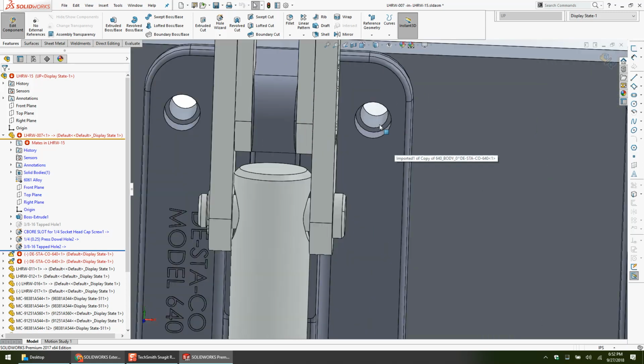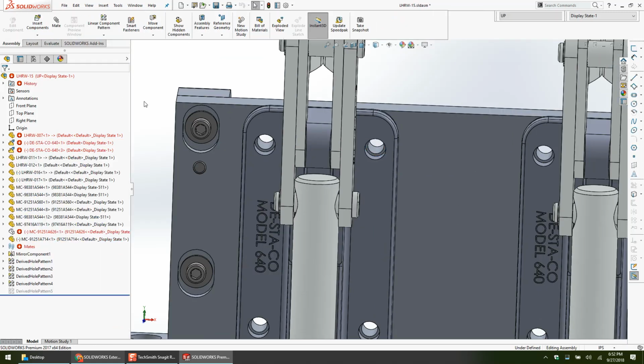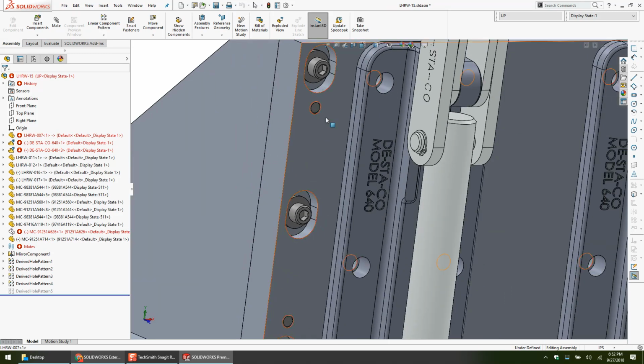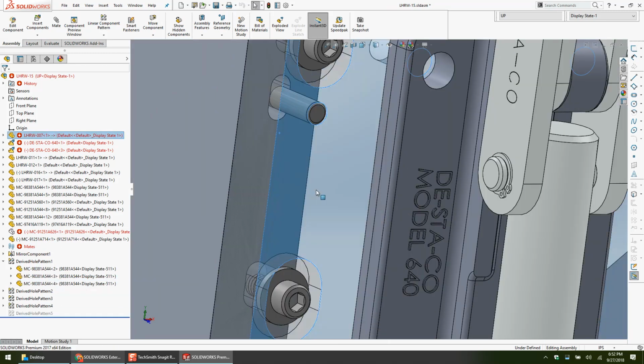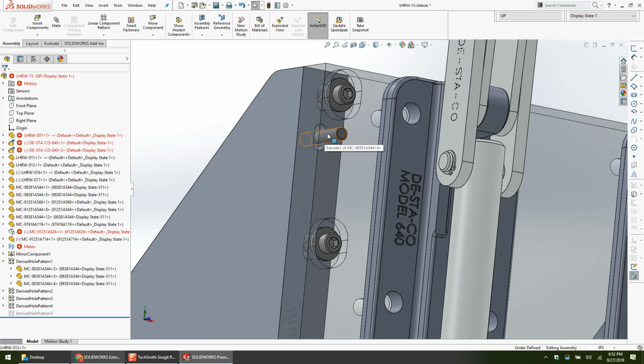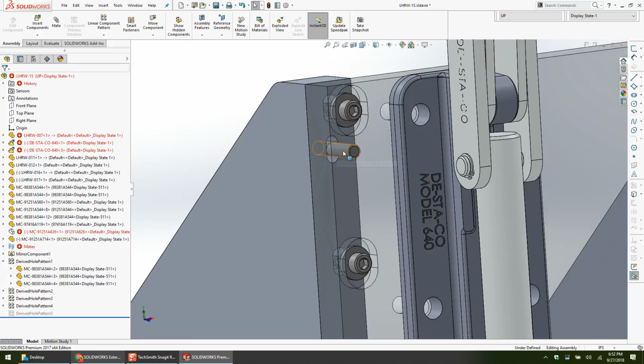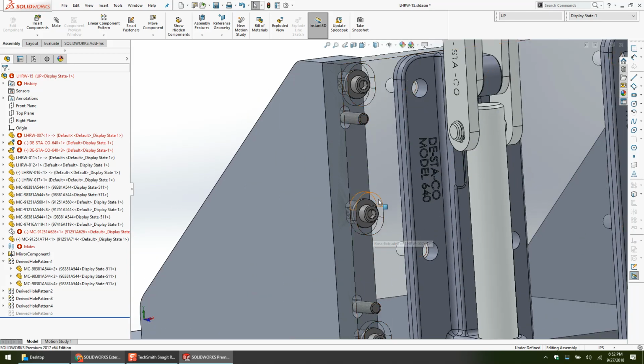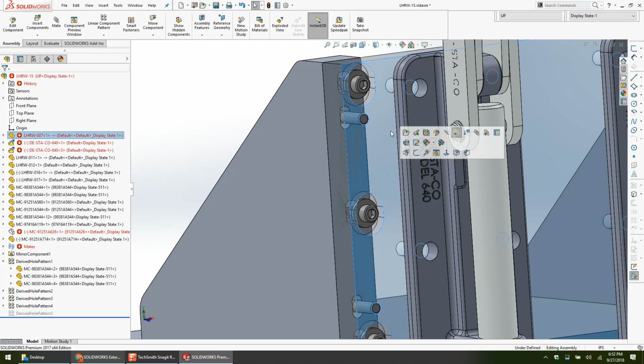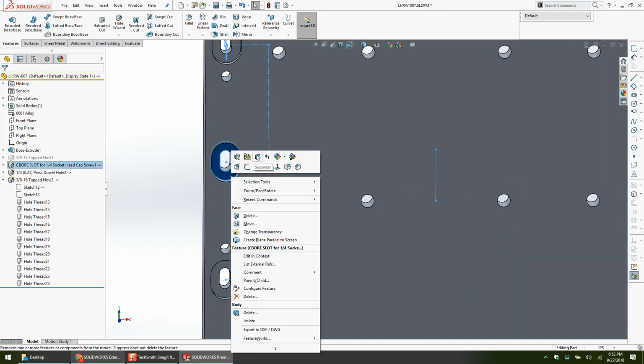So this was pretty easy because I had through holes on the Destaco clamp, right? We all recognize that. These dowel holes had to be adjusted, so their dowel holes are slotted in the fixture and pressed into the plate, and then my counterbore holes are slotted here. But my dowel holes are a little bit more difficult. We'll pretend we don't have counterbore holes.